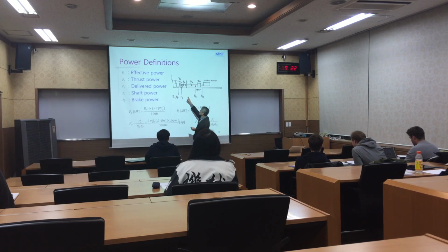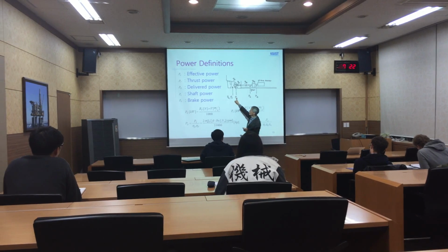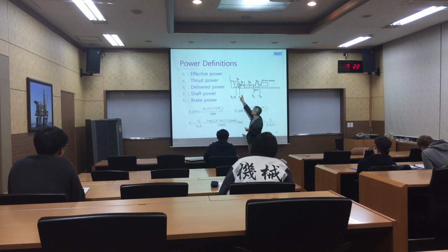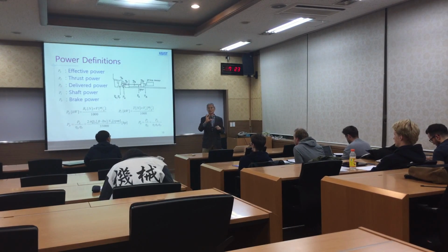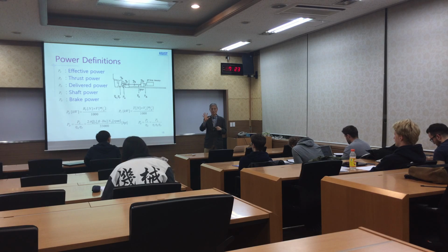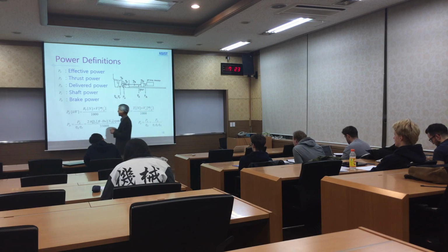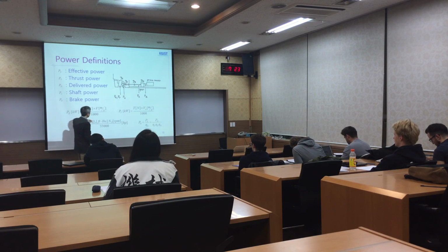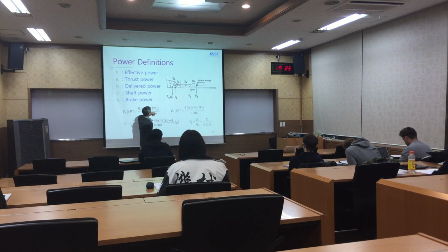And then just after the stern tube, we call this the delivered horsepower. And that is converted into thrust by using a propeller. And the propeller gives you power to propel, right? And usually the efficiency of the propeller is around 60% or up to 70%, but not more than 70%. And this one is the same: effective horsepower and thrust horsepower are the same.